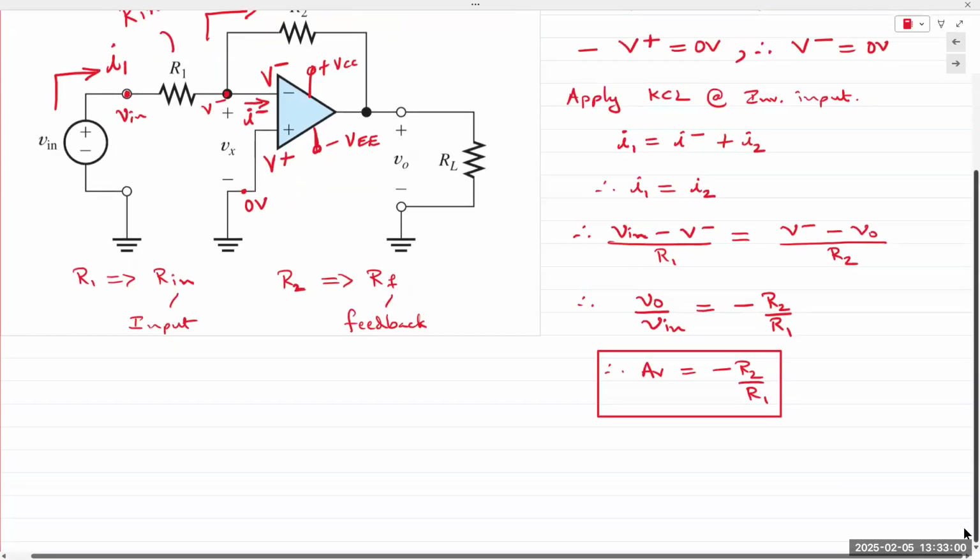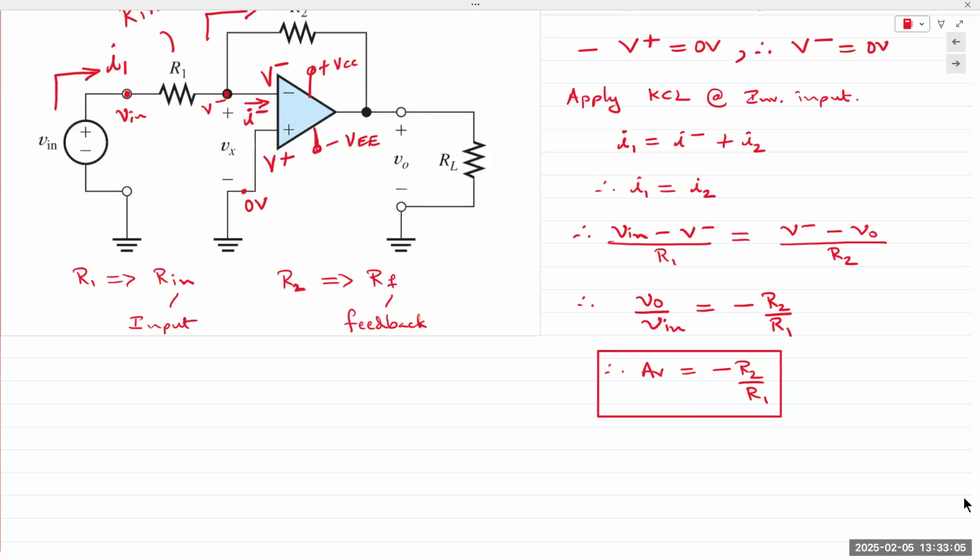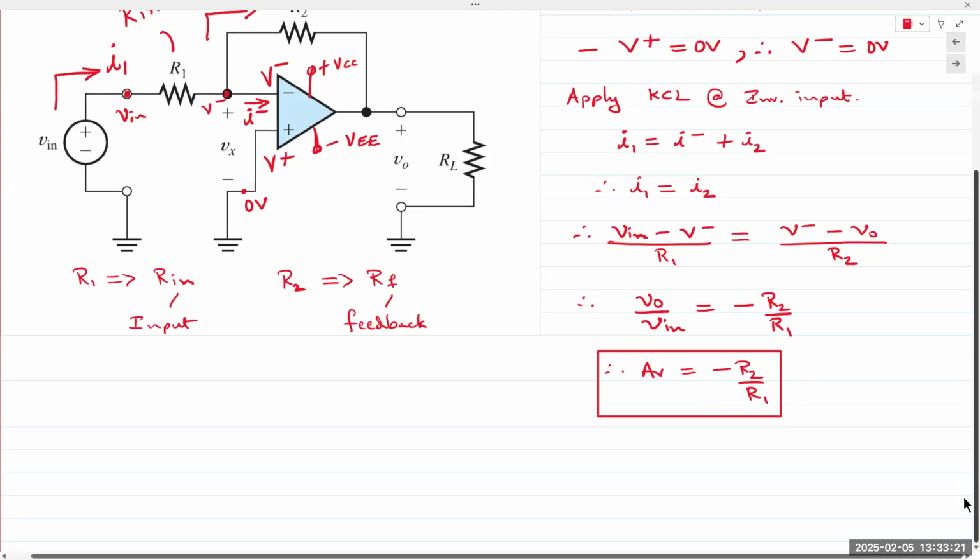This is by far the simplest and most straightforward of the amplifier circuits. But one of the downsides is that if you wish a specific gain, you are limited by the design of the circuit. The gain is limited to RF over Rin, or R2 over R1, and resistors are only sold in specific values: 100 ohms, 220, 330, and so on. So if you want a very specific gain value, then you have to create a slightly different circuit with more resistors in the feedback path. I have that problem later on in just a couple of slides.